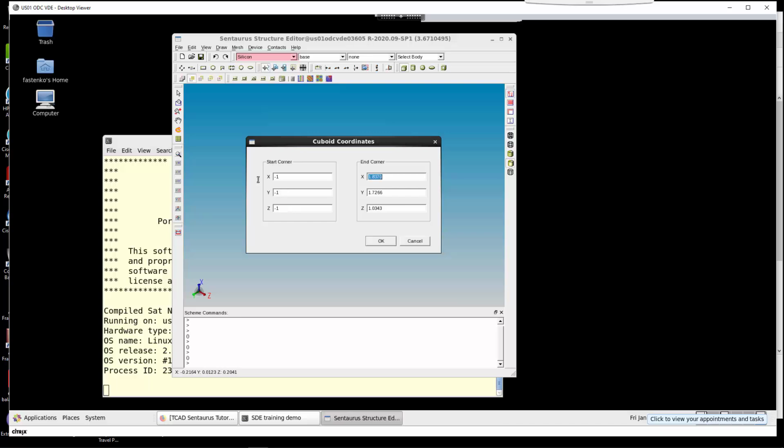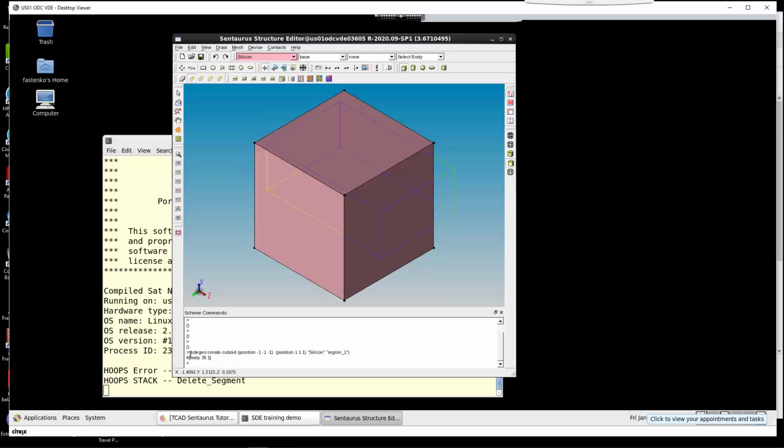Defining a complex device structure involves experimentation, which can lead to errors and even crashes. Performing a long sequence of operations in the GUI is often problematic. One way to generate and maintain this script is, after each user interface-based operation, to copy the echoed Scheme script command from the command line window to a text editor. After that, edit the script if necessary and copy the script back to the command line window.